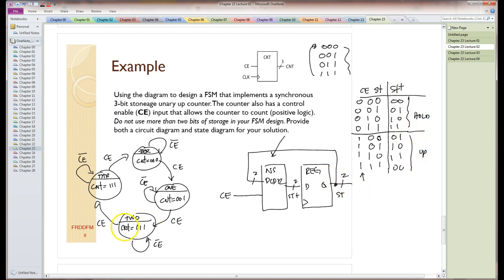The issue here is we haven't put the count in there, and so we need to put the count in there. The only way to do that is to drop another circuit on the front of this thing, and the output is going to be count. The issue is there are 4 states. The output does not depend on whether it's being held or not. The output only depends on the state. So for this decoder here, all we need to worry about is the state.